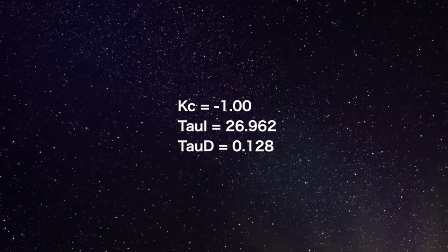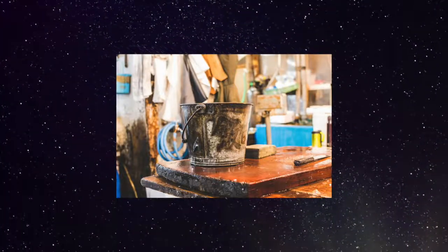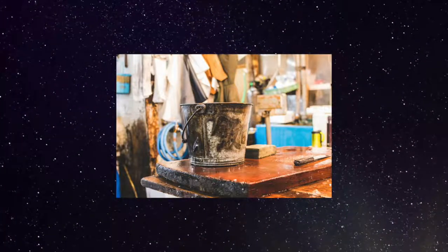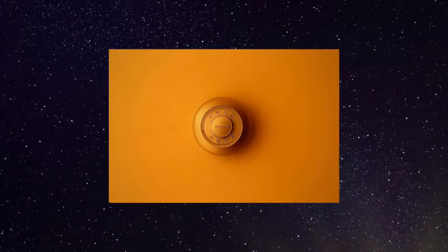However, upon plotting our controller and the system responses, we noticed that the desired inverse relationship was not showing up. We tried a plethora of tuning combinations and still to no avail. A colleague of ours noted that our system was an integrated system, meaning that it never reaches steady state, as long as the controller continues to input signals. For example, a water hose filling up a bucket will never reach steady state because it will continue to overfill indefinitely. Contrast that with a thermostat that will increase the heater output until the desired temperature is reached.